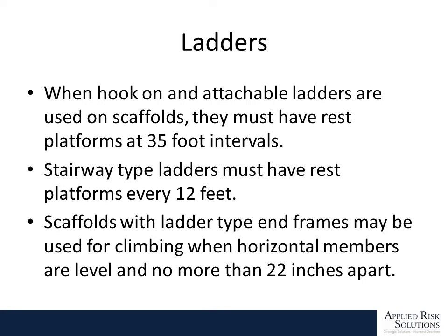Ladders. When hook-on or attachable ladders are used on scaffolds, they must have rest platforms every 35 feet. If you're using stairway type ladders, you've got to have a rest platform every 12 feet. And if you've got scaffolds that have end frames with the ladders built into them, it's okay to use those for accessing up and down as long as they're level and they're no more than 22 inches apart.